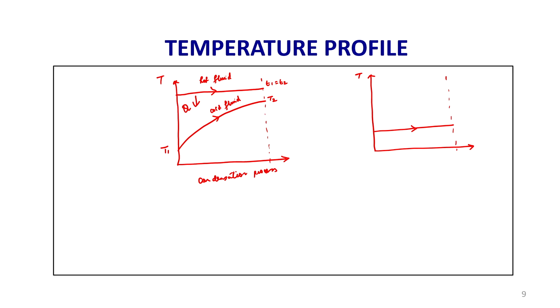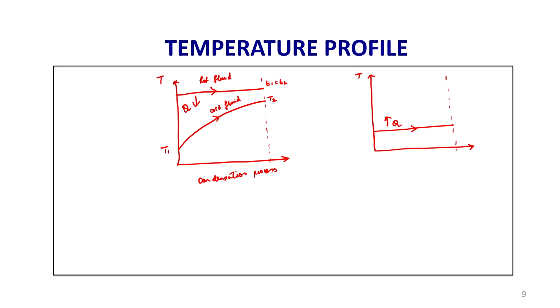Okay. And what happens during evaporation, the fluid takes the heat, so the direction of heat flow will be from here. Suppose you are cooling the water, initially the water temperature will be more, but the final temperature of the water will be this one. So, the refrigerant removes the heat from the water, thereby it vaporizes, and again it is an isothermal process. So, it will be like this.